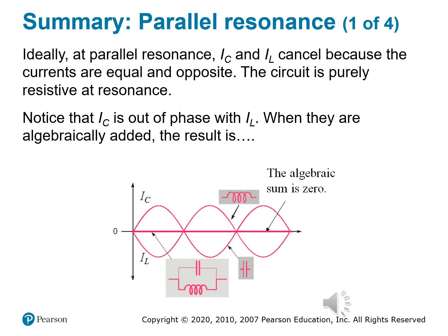It's minimal reactive power. There's very clean behavior here, and you have a maximum calm here to this chaos. Now, what I want to stress is that minimal reactive power. We talked about this prior to here, and this is where it all comes into play. But don't forget, this is the opposite of what we saw in series resonance, where the inductor and capacitor voltage is canceled, right? Here, it's their currents. So parallel, it's their currents. Series, it's their voltages. We're going to keep making those same relations from now to kingdom come.